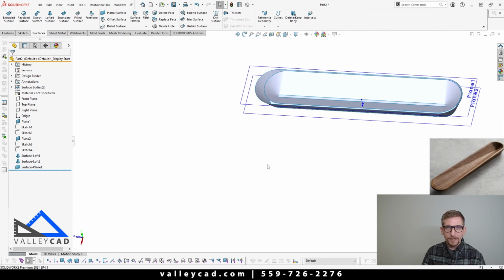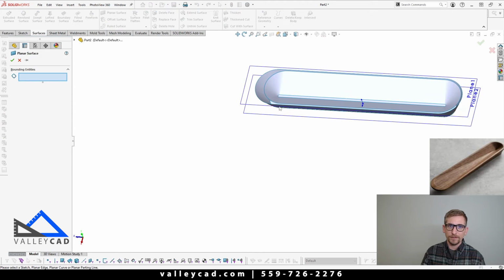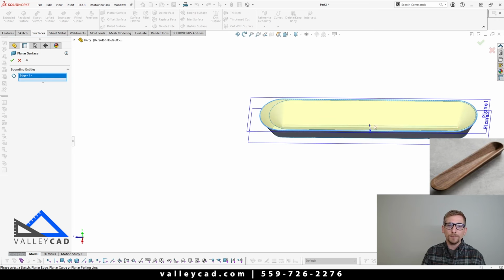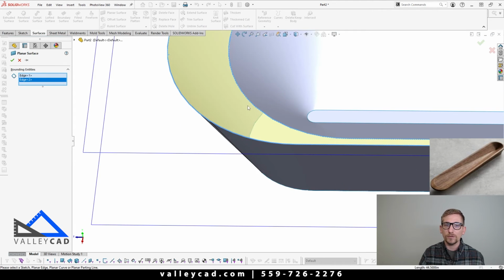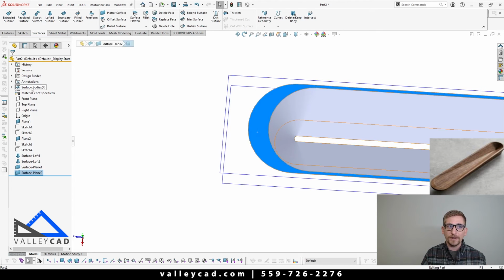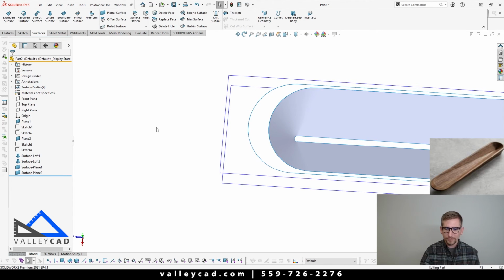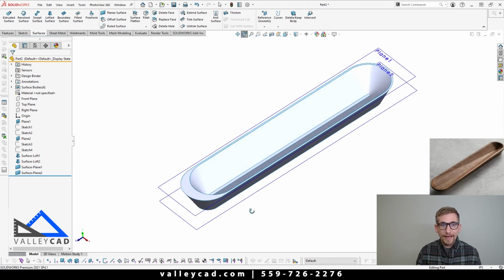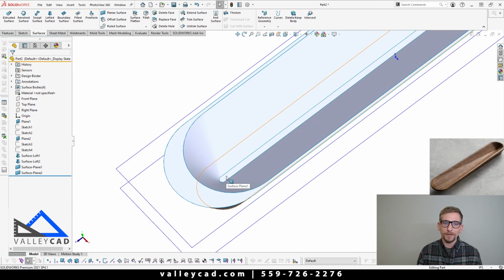All right, then from there, I'm going to do another planar surface. I'm going to do it from this edge to this edge, because if you see here, without clicking on its inside one, SOLIDWORKS is just trying to fill in that entire perimeter. So what we need to do is just click on this inside edge, and SOLIDWORKS will knit it up nicely in between. But once again, these are individual bodies. You'll see here I have 4 surface bodies now. Okay, now you will notice that I do have an opening at the bottom here, right?